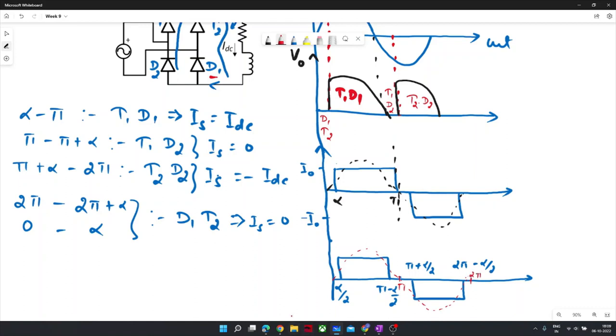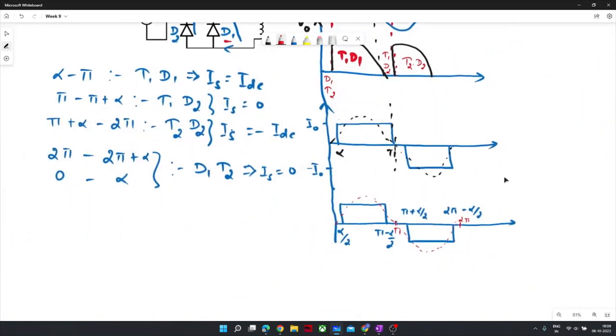And that factor, since in full bridge thyristor based rectifier, when source is not freewheeling, when source is continuously conducting, then this would have been a full square wave. But now some portion gets chopped off, so that portion would reflect in its expression.